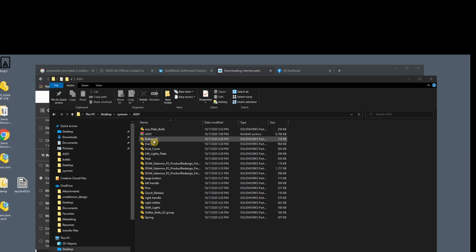The biggest difference when you do the Pack and Go is that when you have that assembly, it will take everything. Doesn't matter what folder it's in. If it's associated to that assembly, if you've got 2D drawings, spec sheets, the 3D parts, FEA analysis, when that window pops open, it asks if you want everything to be part of this. You can click what you want and don't want, and it makes sure it all goes right in, because there are times where your 2D drawings may be saved somewhere else. That's the nice feature of the Pack and Go.